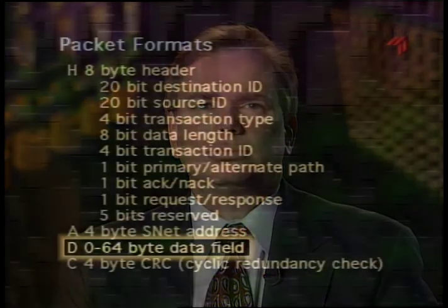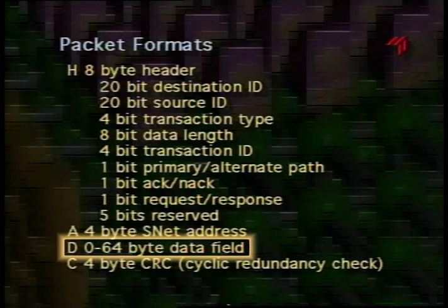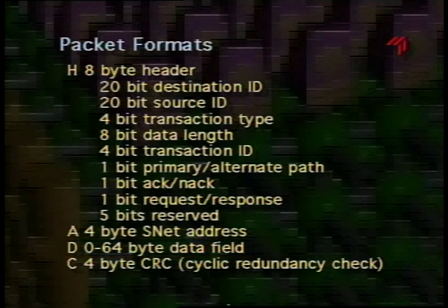The address validation table also includes access rights to make sure that the packet was allowed to either read or write that destination. The packet also includes a variable length data field with 0 to 64 data bytes. This data field was intentionally kept fairly short for fairness in the network. If we had allowed very long packets, then the maximum latency in the network would have been long because the high priority packet might be stuck behind a large number of long packets before it could be delivered.